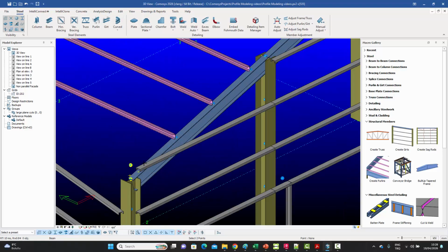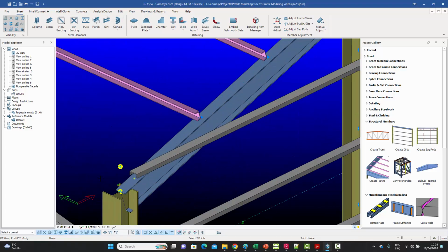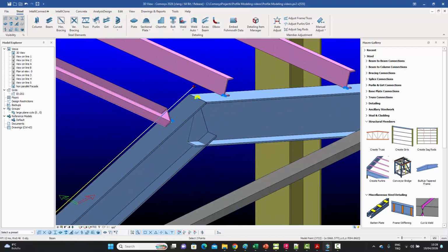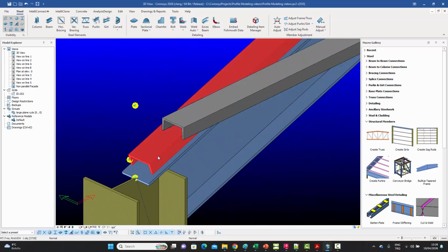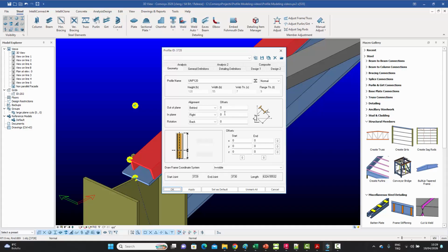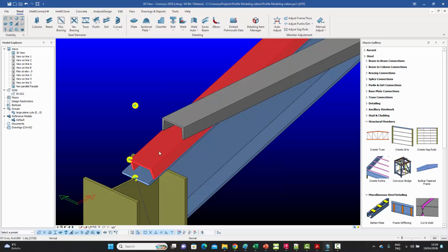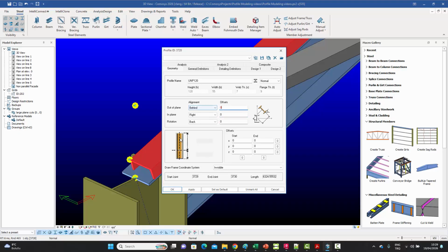So you could go in there and use this point rather than the point of the roof beam, and then a similar point on the other side as well, like that. And now what you could do is you could select this and press Control W to bring it down, and give it the offset of 150. Before we do that, no, we need to give another offset because this distance was 100. So I'll give it 100 to bring it down to the same level. So now it's exactly at the level of the roof beam, but physically it's separated. And I can give this one an offset of 150, like that.